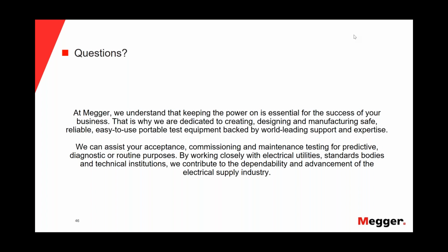I mean, there is no baseline, because the factory has proven by doing their own test that it is basically not PD free, but it's down to that 5 picocoulomb level. You can run a field test where you cannot have this perfect shielding, and you will have a certain background noise, and you still can see whether you have PD or you don't have PD.